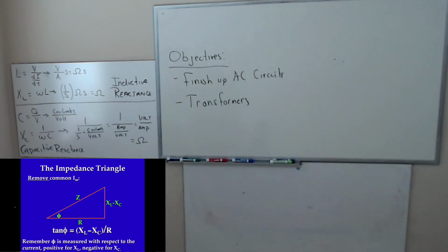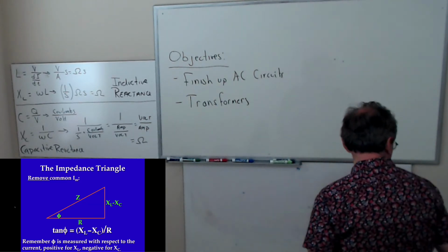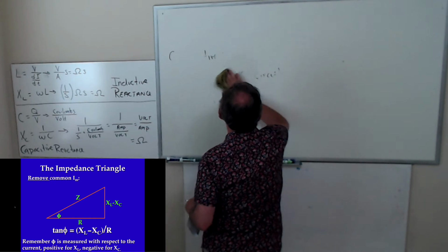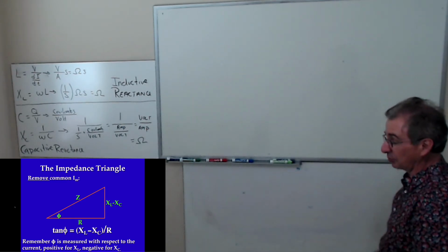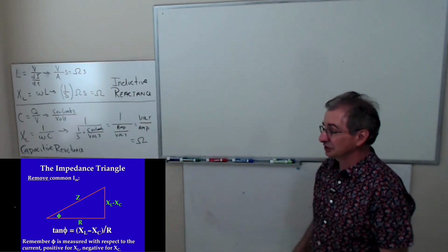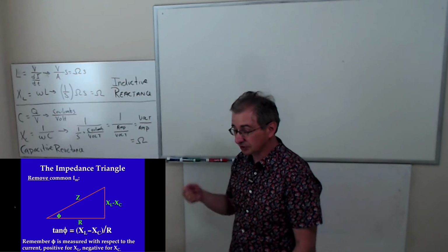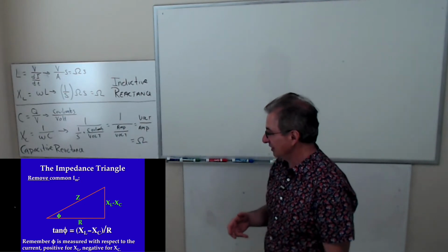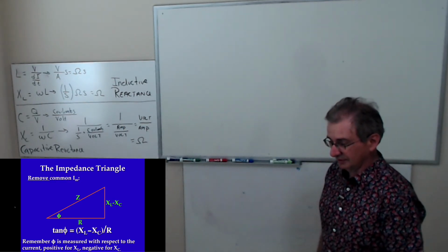I have a question. Sure. It is not on the units. For the RLC circuit, when the X sub L is equal to X sub C, does that mean that the circuit behaves in a way as if the inductor and capacitor were not present? Correct. I mean, from a standpoint of voltage, there's still a voltage drop across the inductor, and there's still a voltage drop across the capacitor, but they're equal to each other. But they cancel out, right? Yeah. And so basically, the voltage drop across the resistor is the power supply voltage.